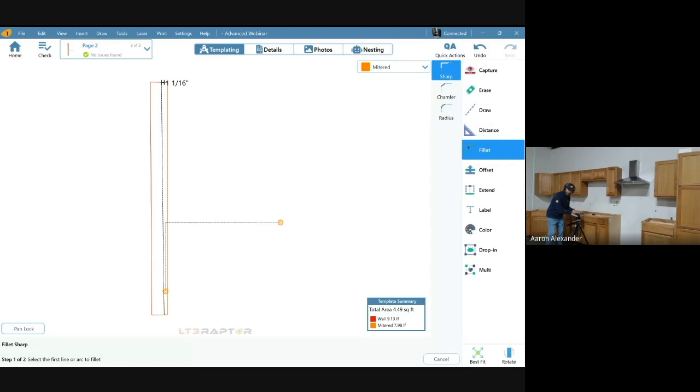So I like to get my laser at this height. Again, our laser's just above here, so I can shoot right on the 1/2 inch line on the block down there, and I can shoot right on the 1/2 inch line on the block down here. I get 0 laser stretch because we're shooting directly onto that target back there. So we just took laser stretch out of the equation, and we'll just offset that line down that 1/2 inch to get us our actual edge in space, right?